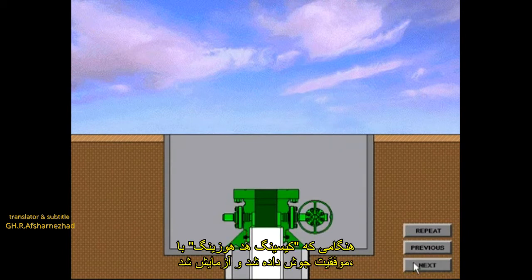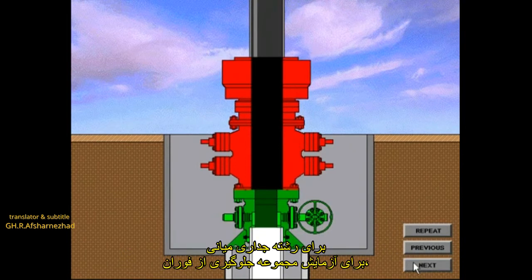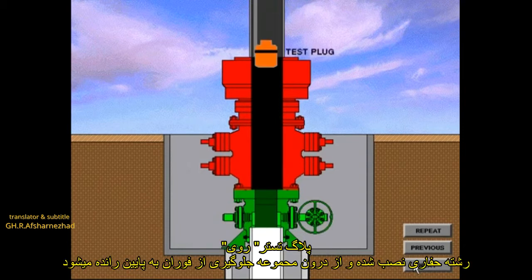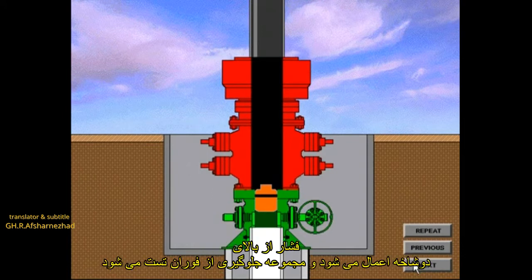When the casing head housing has been successfully welded and tested, the BOP system is installed or nippled up, and preparations are made to drill out for the intermediate string of casing. To test the BOP system, the test plug is made up on the drilling string and lowered through the BOP system until properly located in the casing head bowl. Pressure is applied from above the plug and the BOP system is tested.